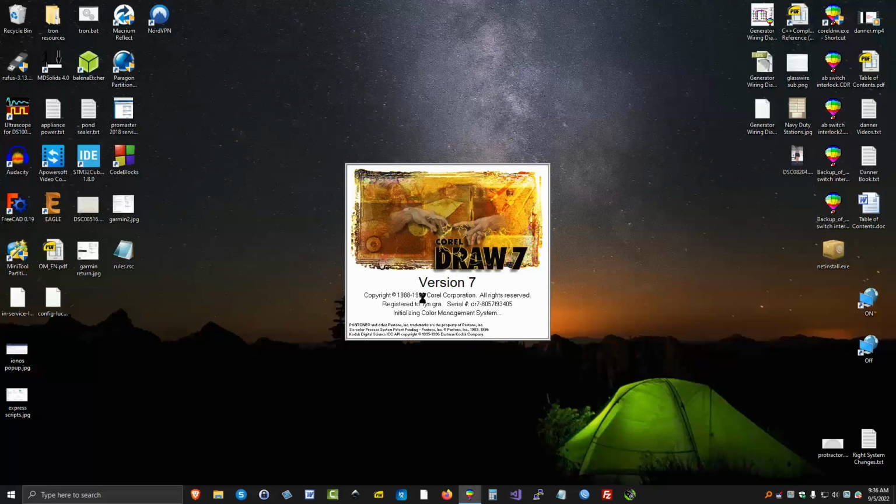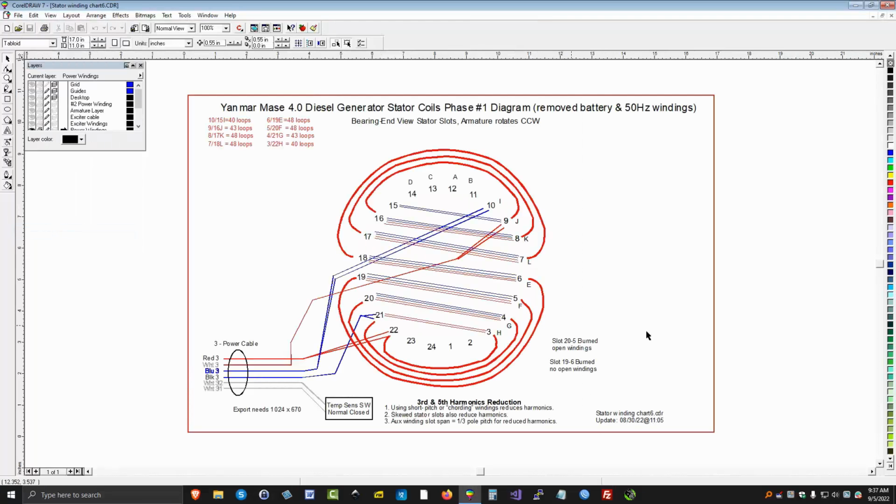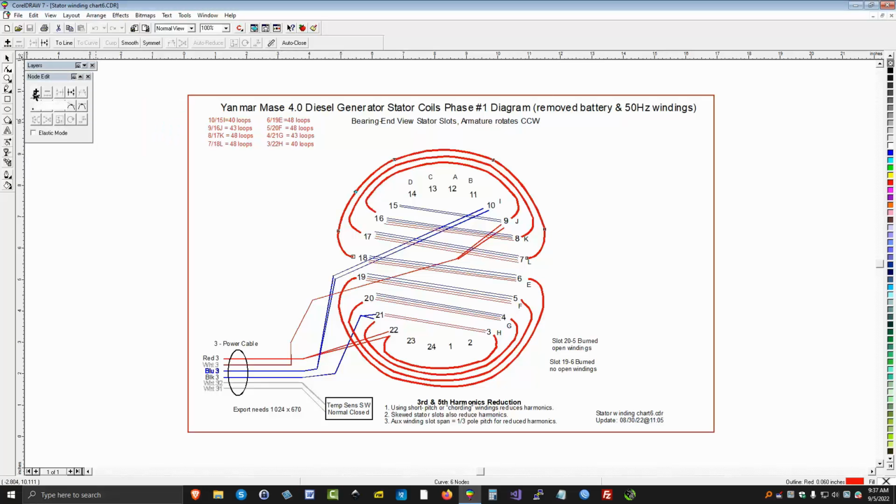So restart it again. Reload chart 6 for a minute. It's got some interesting things going on. So if we select something, let's say we select this particular line here. It's actually a line turned into a curve by using this tool up here. We talked about it earlier. I can take a straight line. If I select this tool, notice I get these little squares. See these little squares right here? You can add more squares. Just double click on a spot and it lets you add a new node point, which is what they call it.